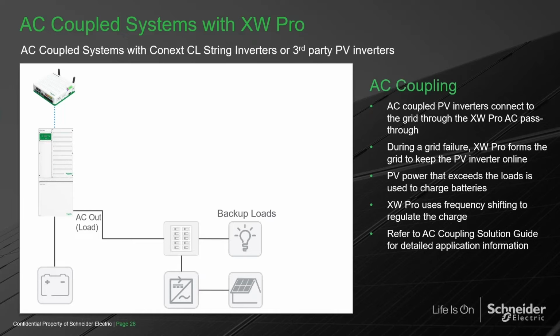Okay, so the first thing that happens here, and this is again a power outage, a full-blown power outage, or it could be a brownout where the voltage is dropping or is unstable. The XW Pro's internal relay, a mechanical relay, will actually open, isolating this. We're going to call this a little microgrid. So now the functions inside the house are completely isolated from what's happening out to the grid. So there's absolutely no danger of injecting out to a grid that is having problems.